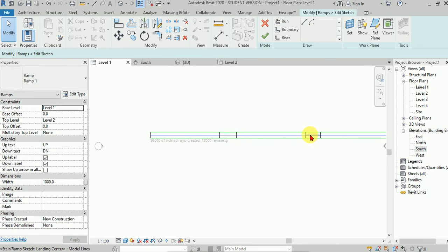Why is this mid landing even there? Similar to any staircase, after 10 or 11 steps you have a mid landing. Why? Because it's not feasible for a person to climb a single flight of more than 10 to 11 steps. It would tire the person.